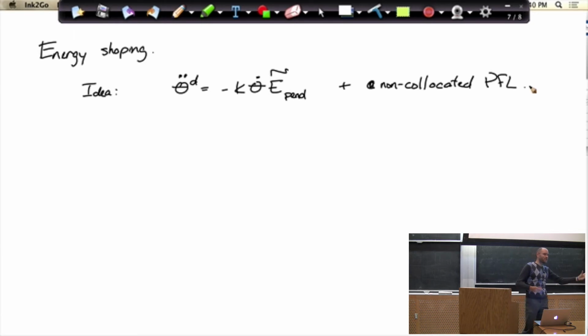And that works. Mathematically, it works. The problem is it's got that singularity, and so that actually means there's going to be times where I'm going to try to push infinitely hard on my cart, and that might not be something you want to do with your actuators. And here's where you get to think like a nonlinear dynamics, nonlinear control guy again. There's a nice manipulation of the algebra that works much better than this. It gives you a much better controller that'll be more robust to the parameters, doesn't involve infinite force, and it's going to use all the same tricks.